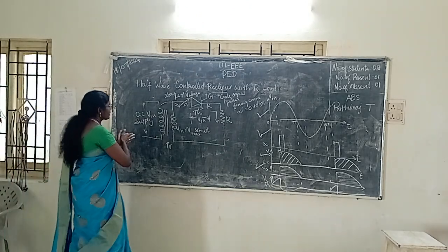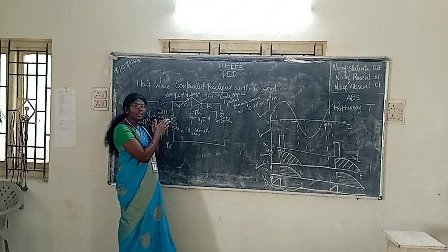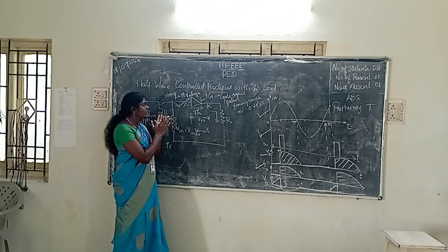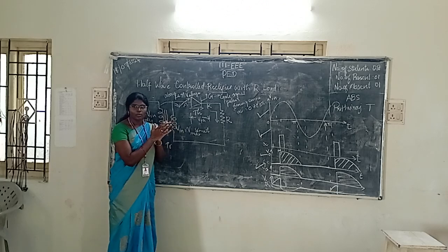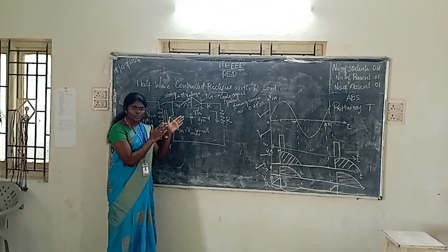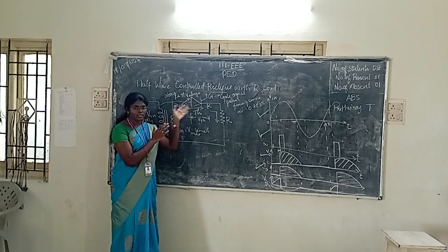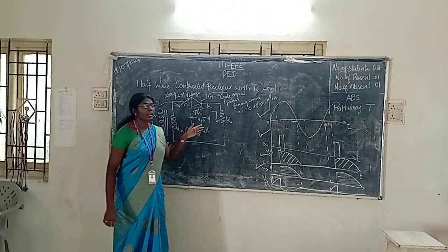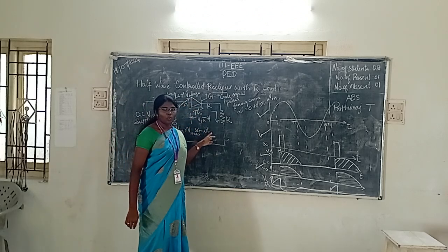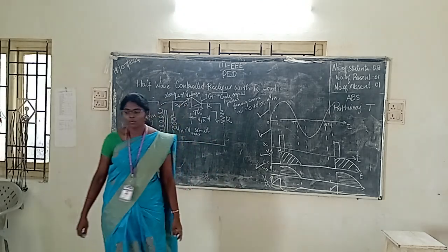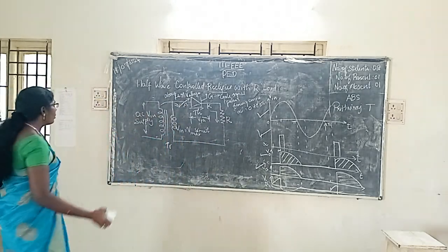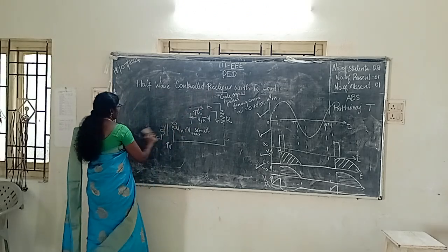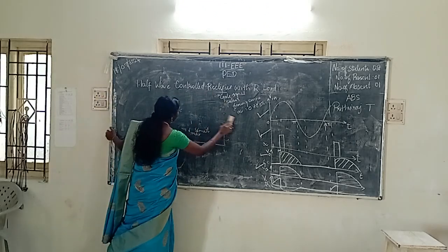After giving this initial voltage, which should not be greater than the thyristor's forward and reverse voltage rating, the thyristor will conduct in forward bias since the anode is connected to the positive, and the next terminal is the cathode. We control it using the gate signal, and we are looking at the resistive load. Based on this, we have to derive some formulas for the output voltage. So what is the input voltage we are giving?